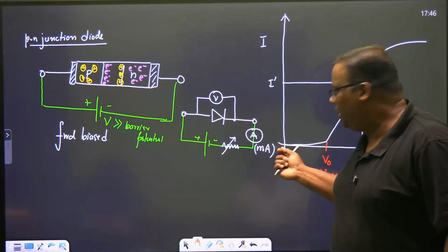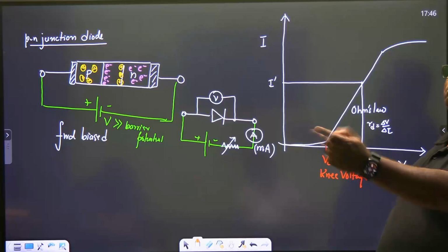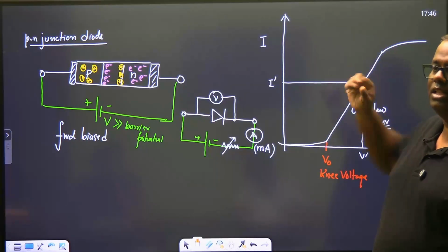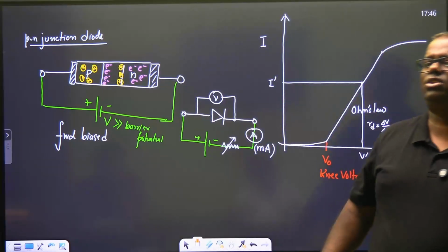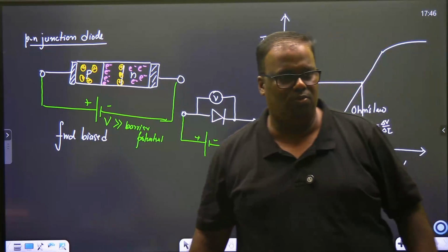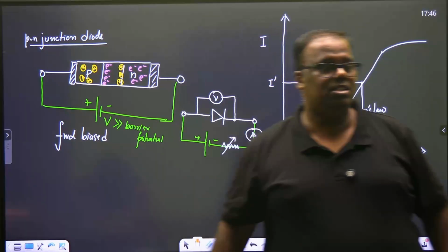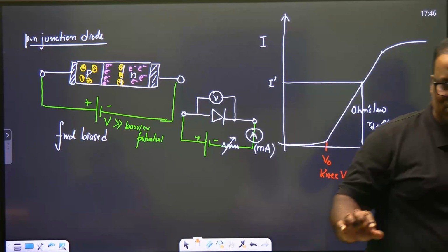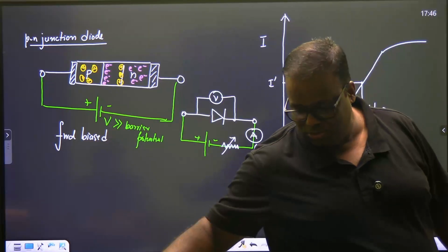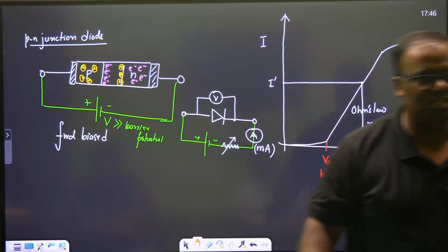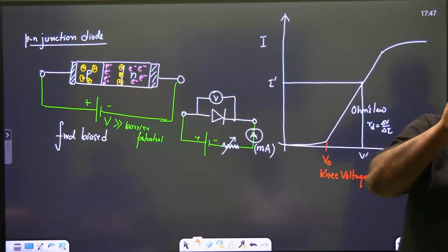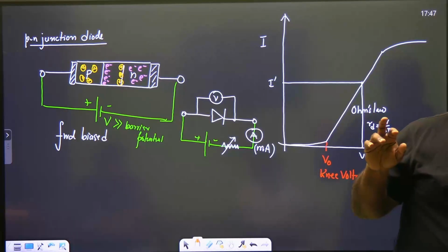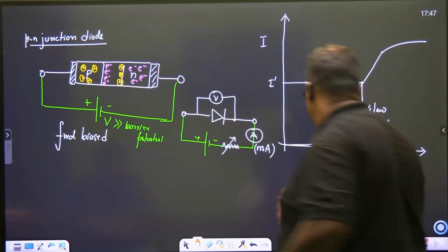You will go by an experiment and you will see that at a particular voltage, I start getting a linear characteristic. That minimum voltage at which a diode starts conducting is known as the threshold voltage. Actually we get very little time, otherwise we could show you on breadboard experiments also. You can put an LED, put the diode, put 3 volts across it, and the LED will glow. Okay, see how to do this.